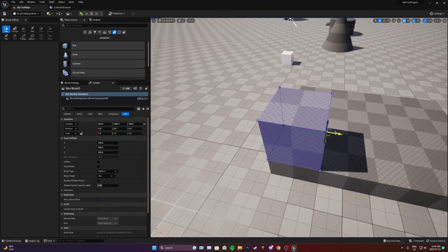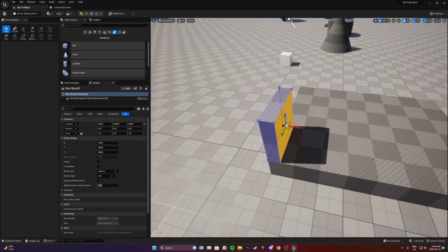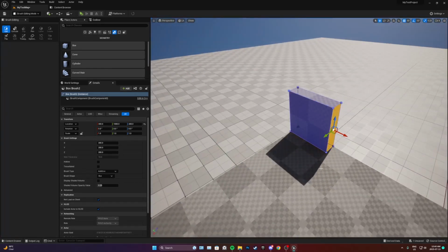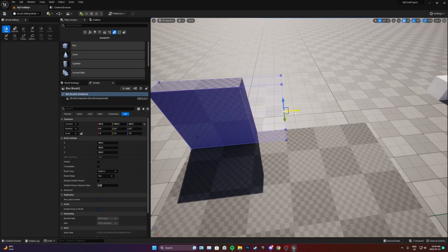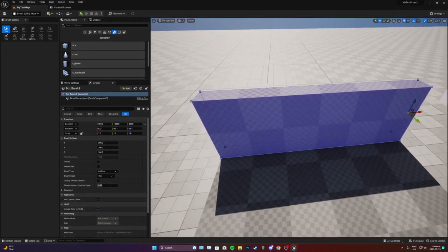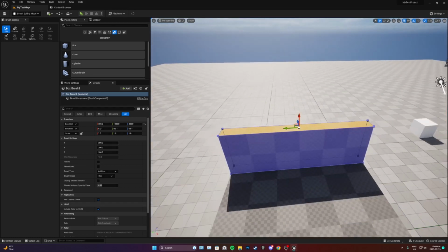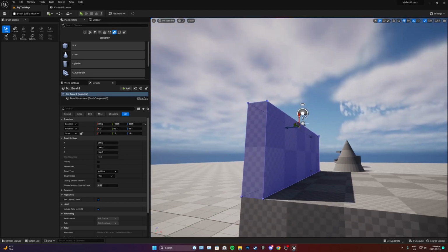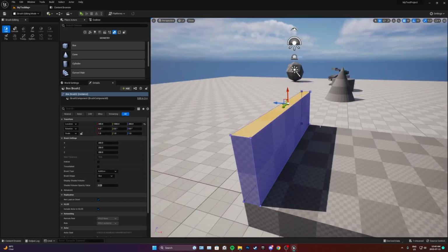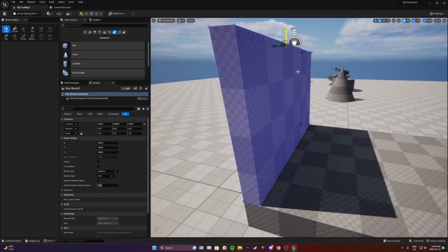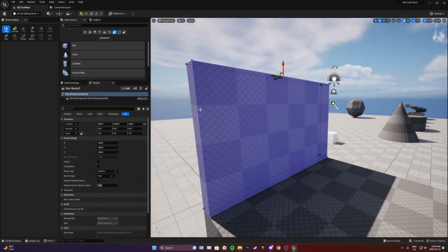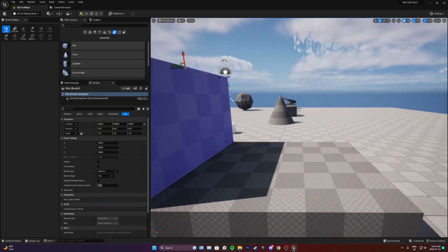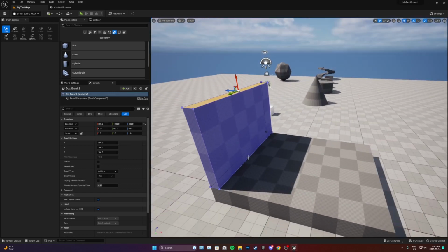And then I want this to be like a wall, so I'm just going to make it 50 wide. When I say 50, it's actually 50 UUs, which is Unreal Units is what we call it. But it actually converts to meters. So each UU is a centimeter. So 100 UUs, one of these boxes is 1 meter by 1 meter by 1 meter, which is really cool. So you can convert things that way from a modeling software that uses meters or something.